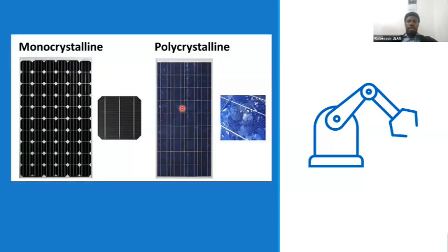Also we have another type of photovoltaic module, the amorphous photovoltaic module, and also the perovskite cells, and there are some other types of cells under investigation that are not available on the market. But the most available on the market are the mono photovoltaic module and the poly photovoltaic module. Also, we have some amorphous photovoltaic modules that are available on the market.